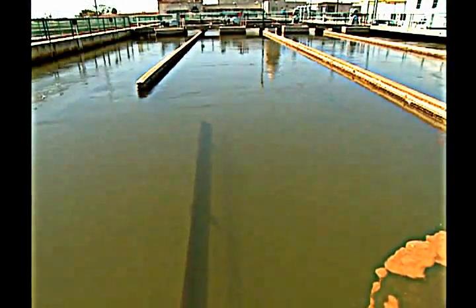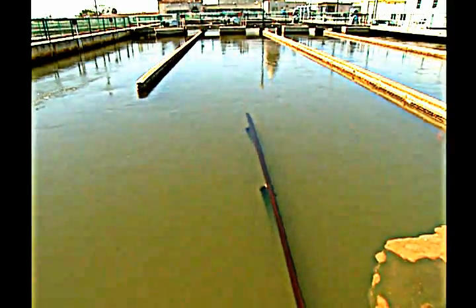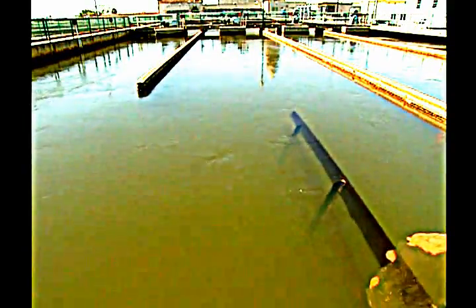You need to add enough energy to the water to gently stir the water so that the particles come together and stick, but not so much energy that they shear apart again. So usually flocculation basins have large either paddles or hydraulic mixing of some kind that's gentle, and that'll allow the particles to sort of clump together and form larger ones that can be settled or filtered out.